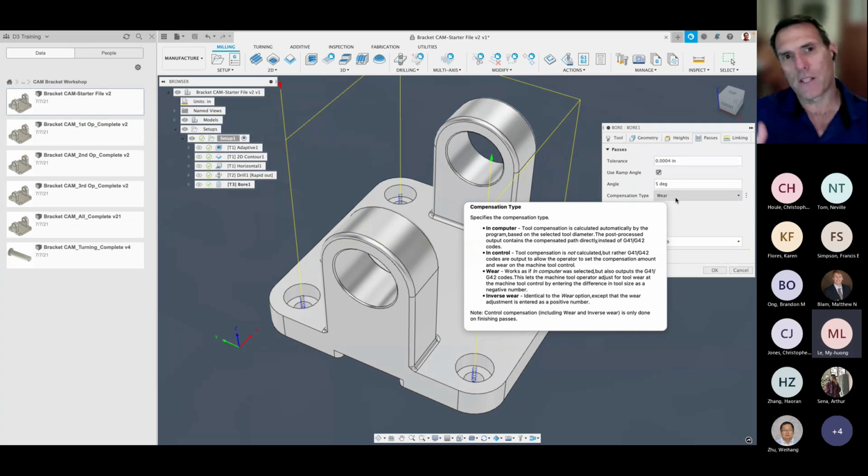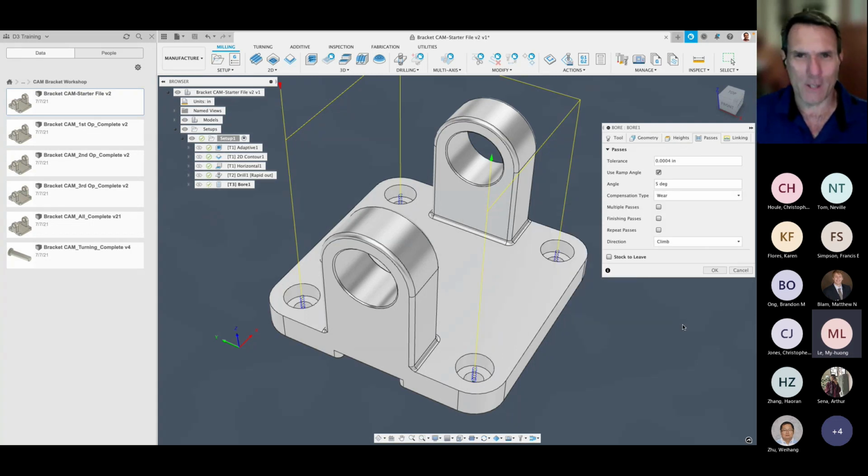But the reason there's differences, I'll just finish that thought. On one of the more advanced CNC machines, you can update its tool library to let it know what the realities of its tools are at that time, and where compensation can make up for that. However, in control or in computer, you might have to put that in manually if you have something like a CNC bridge port that will literally take anything you stick in the chuck and just move it without even knowing. So you have to be semi-manual there.